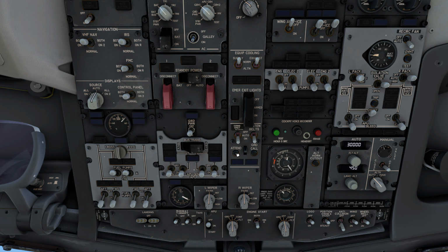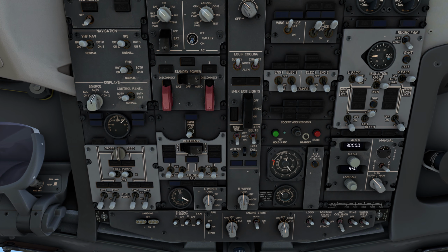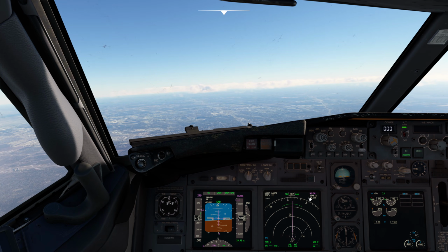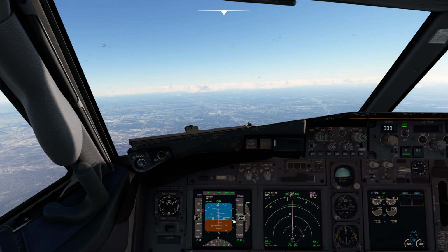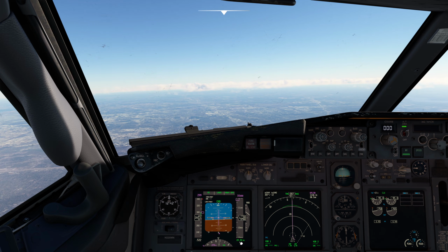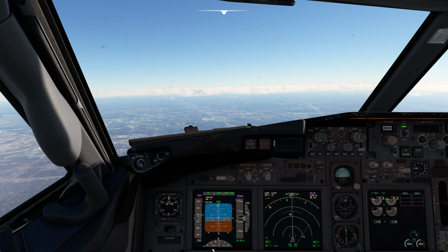We can go ahead and attend. There's the ding-dong you hear over 10,000 feet. You're now cleared to use your large electronic devices. So everything on the upper overhead panel looks good, and we're navving, we're looking good. We're looking for next 18,000 feet for our transition altitude. We're going to switch our altimeters from the local setting at 29.93 over to standard.